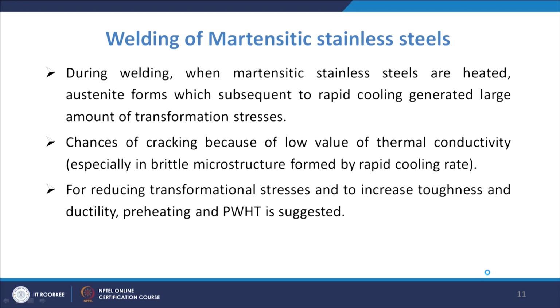If you come to the martensitic stainless steels, which have a martensitic type of structure at room temperature, the problem is that when you heat these steels, austenite will form, and on further cooling the austenite transforms to martensite, so transformation induced stresses are formed.